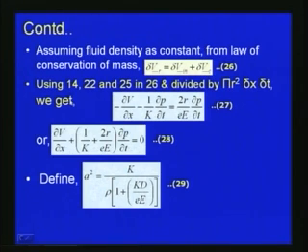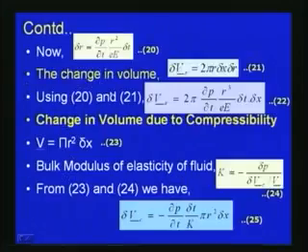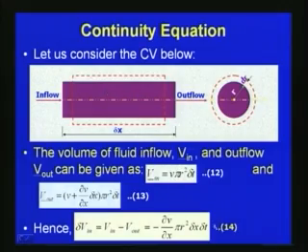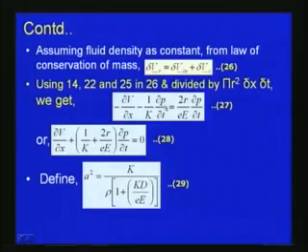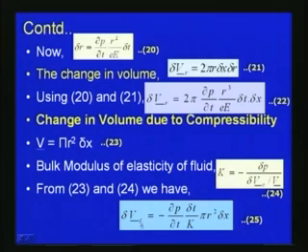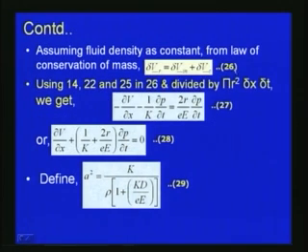So, if we use equation number 14, which we have derived here, and then equation number 22 for del V under bar R, and 25 for del V under bar C in equation number 26, and if you divide by pi R square, the cross section area of the pipe, delta x into delta t, delta x is the length we considered, delta t is the time step,